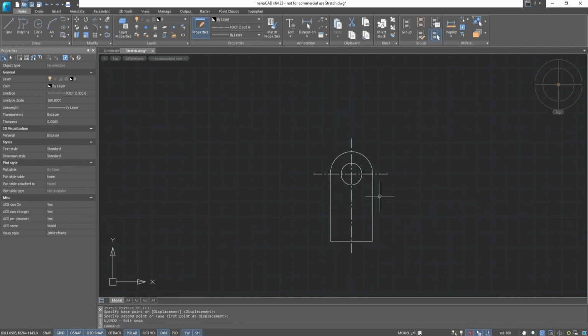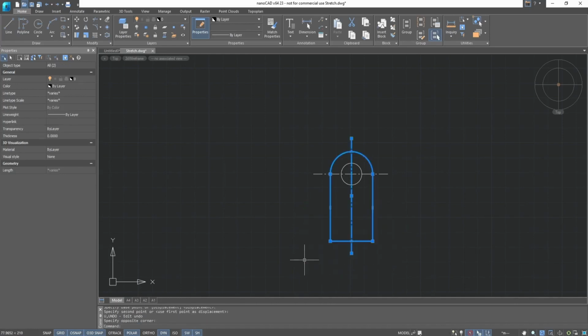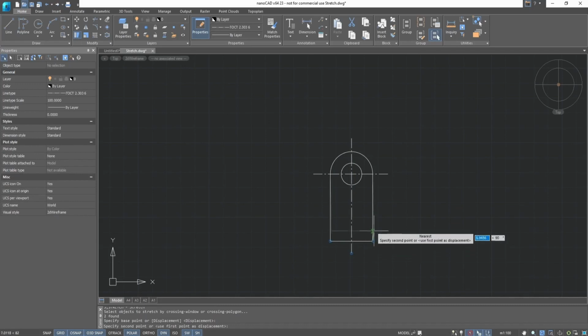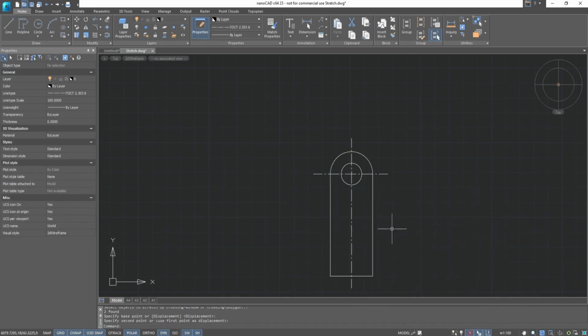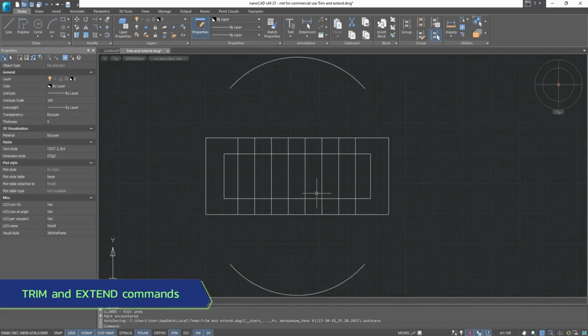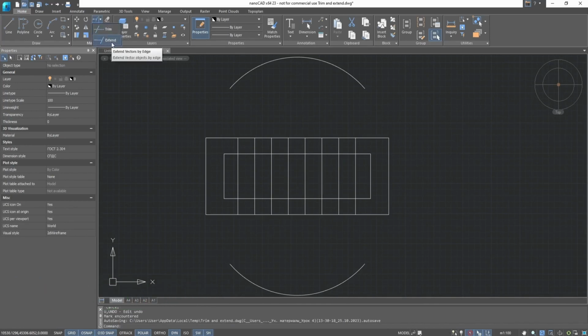However, if we want to enlarge or reduce it, we need to select all objects with a fence frame, then call the command. Now, we can reduce or enlarge this object. Next, we will look at 2 types of commands located in the same area. These are Trim and Extend. They are opposite actions, which can be toggled between during the work using the Shift key.